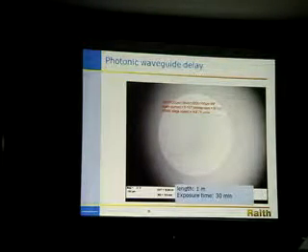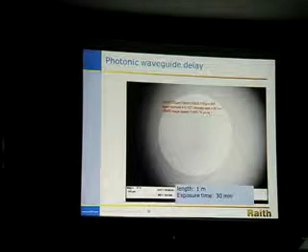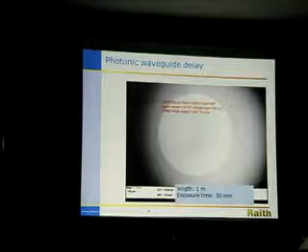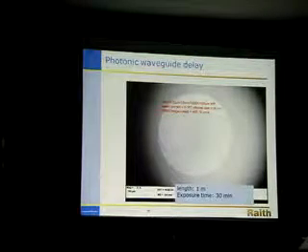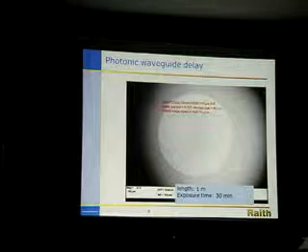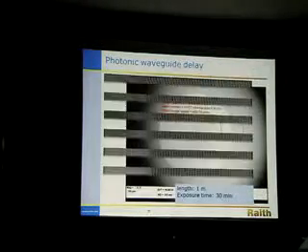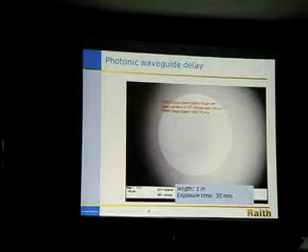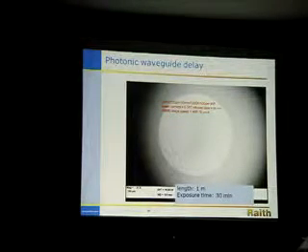So here we have a spiral waveguide device written with electron beam lithography. The scale bar here is 100 microns. The magnification is 31x. So we couldn't even capture the entire spiral waveguide in the field of view. It is 1 meter long. Not millimeters, it's 1 meter long, and it was written in 30 minutes, and of course with zero stitching errors. Our field size would typically be, let's say, 100 microns. So imagine breaking this up into a bunch of stitch fields. You would see stitching errors everywhere, but with tracks, you can write it continuously.